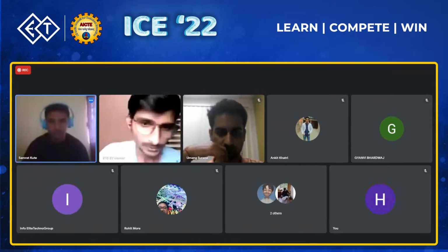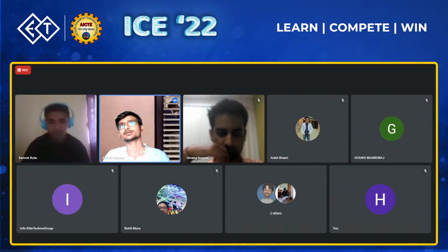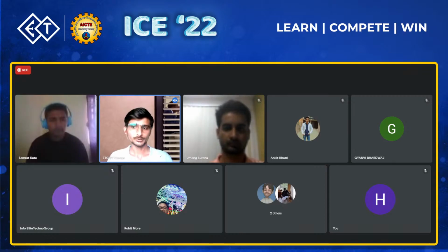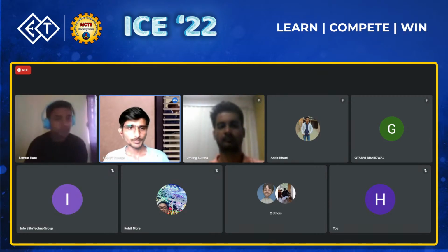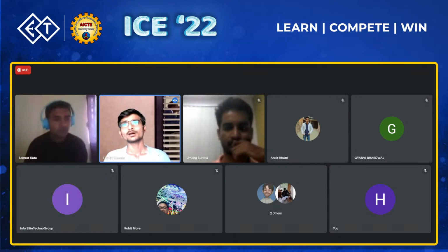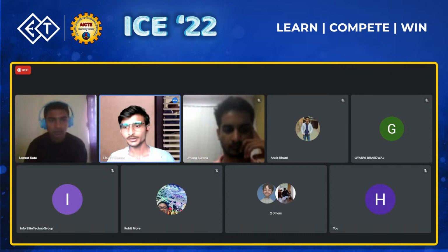Thank you. So, yeah, I guess your assumptions and calculations are pretty accurate. When you're designing a car, your basic motto is to compress your battery pack as much as possible. Even though your number of cells is higher when compared to a pouch cell, the size of the overall battery pack is largely reduced. So that's a big plus, because if the size is small, you can move your battery around pretty easily within the vehicle if you have some dimensional constraints.